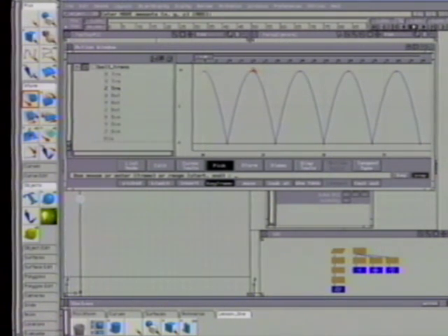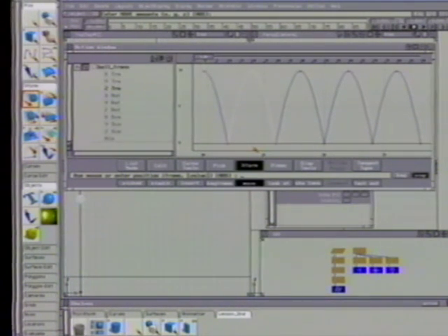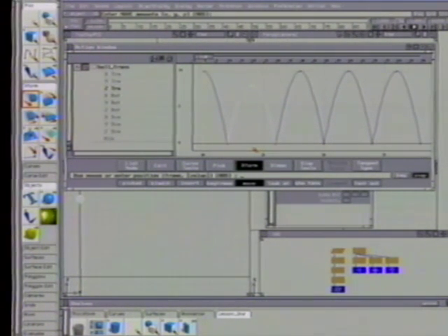From the Action window menu, select Pick Nothing, then Pick Keyframe. Click on the keyframe at frame 20, then select X-Form Move. Enter 20 and 8 to move the keyframe to a Z value of 8. The first bounce will only reach a height of 8 units. Note that the coordinates being entered map time in frames against the Z translation of the ball.